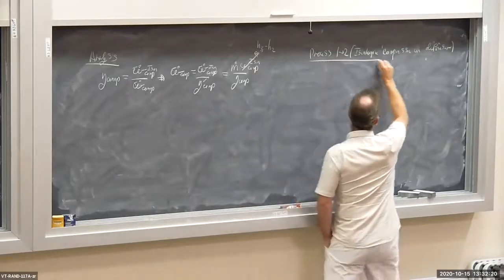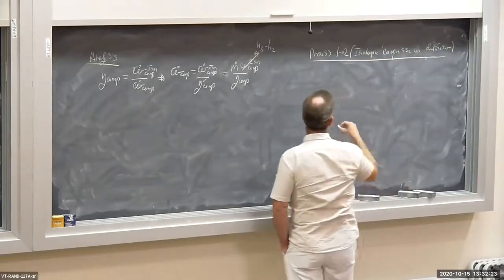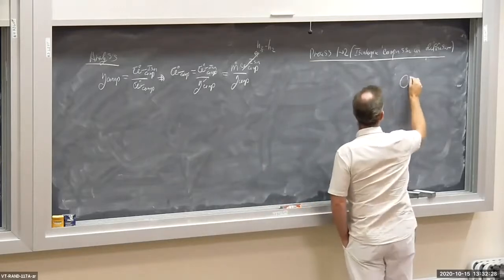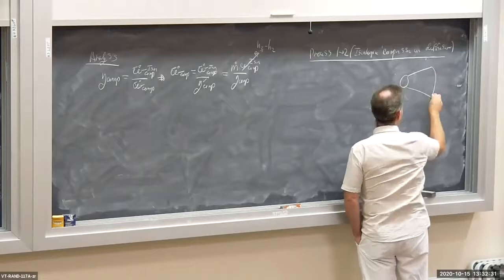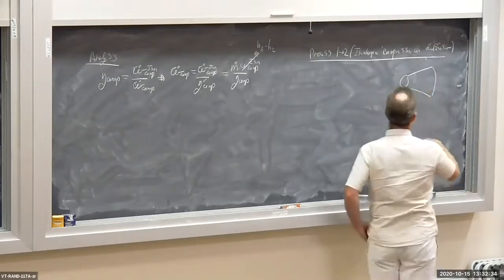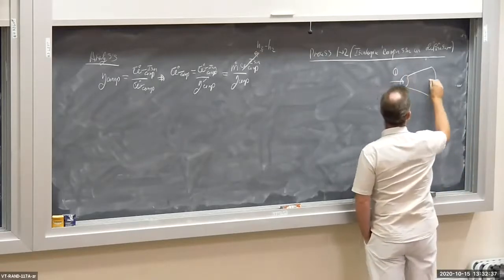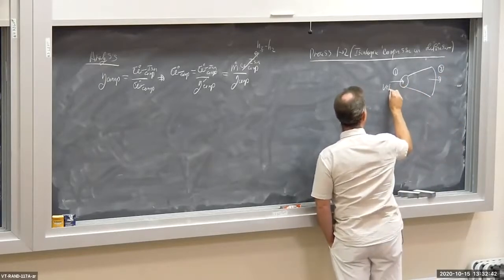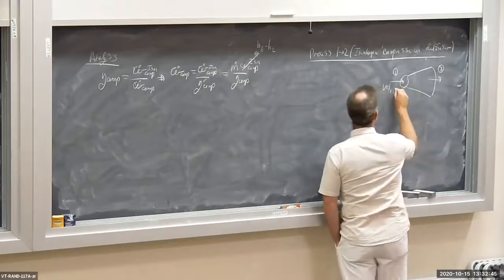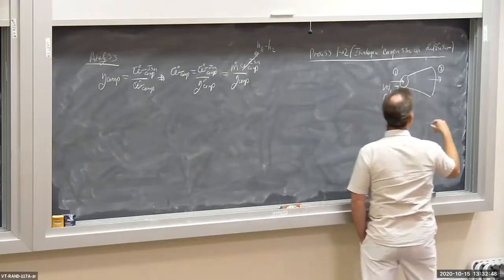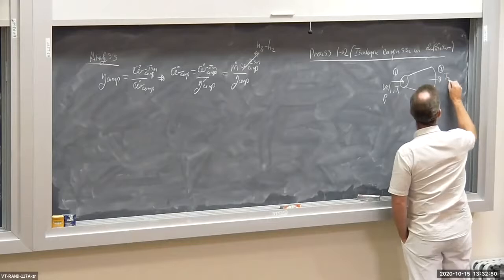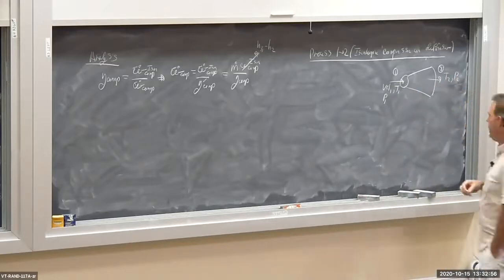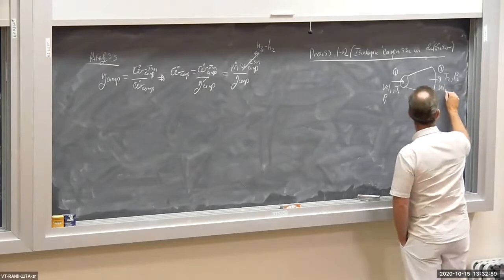Let's apply the energy balance to our diffuser. So our diffuser looks something like this. We have our inlet, the area opens up. Here's the inlet at state 1, here's the outlet at state 2. At the inlet, we have some velocity, and of course a temperature too: T1 and P1. At the outlet, I have T2, P2, and an outlet velocity, VEL2.